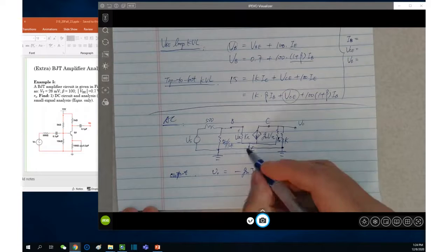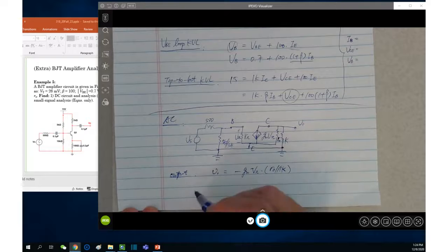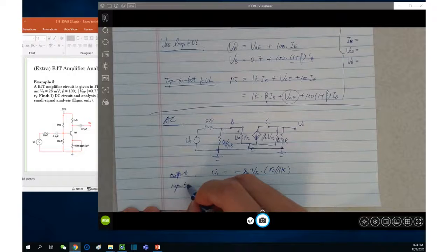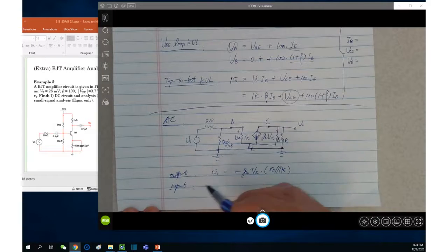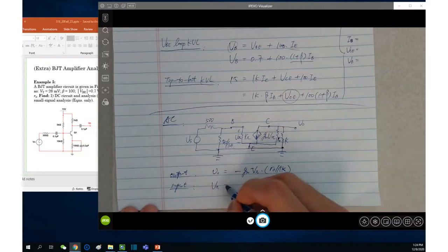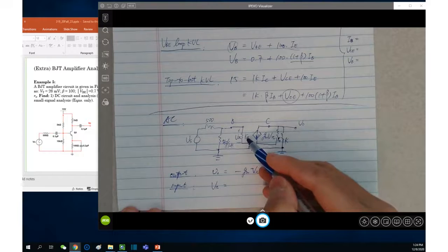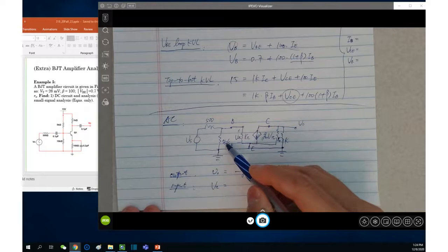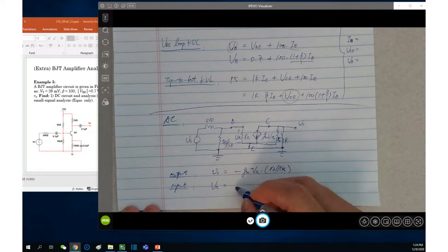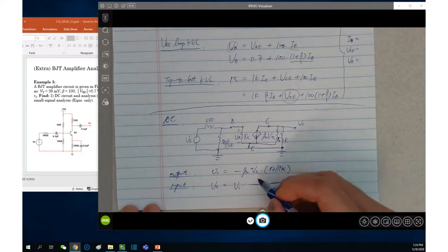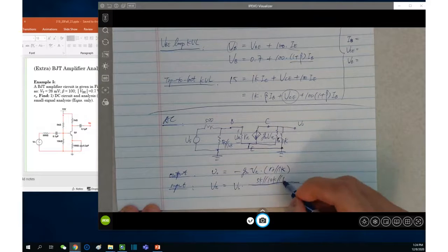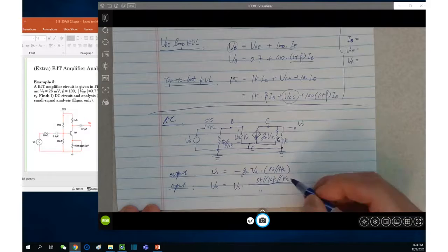Due to here, there's no resistor. So V pi is equal to what? V pi is the voltage across R pi as well as 5K parallel with 10K, right? So V pi equals Vs times the voltage divider. In the numerator is these three things parallel, denominator is these three things parallel plus 500.